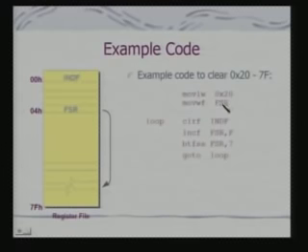Now, you have relative addressing and software relative addressing as well, because when you are doing any of these goto and call, what is the significance of the fact that the most significant bits are coming from the PC latch high register? It means all your goto and call are in a sense PC relative, relative to the current PC value, because the most significant bits of the current PC value are loaded onto PC latch high.